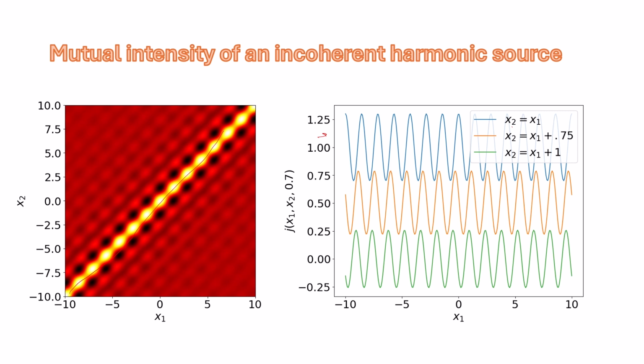But now if we go up here, we're going to make x2 equal to x1 plus 0.75 lambda f-number. So we're looking at a plot that may be up here. Now what you see is that the oscillations are about the same height, but the baseline, the offset, has been reduced. So this would help us improve the signal-to-noise ratio in estimating the high-frequency component of this signal, because its amplitude relative to the DC has been improved.